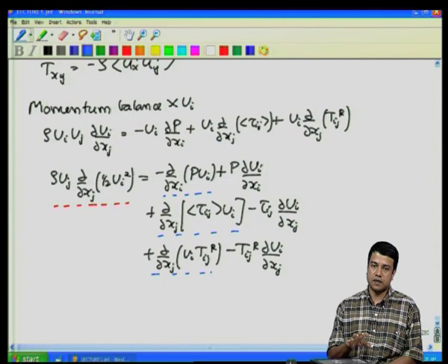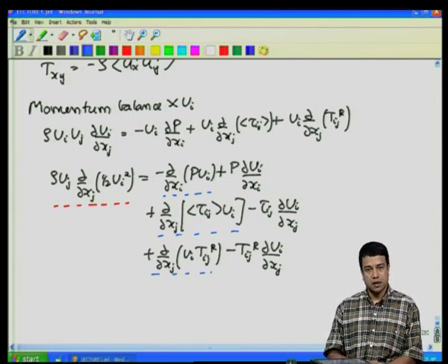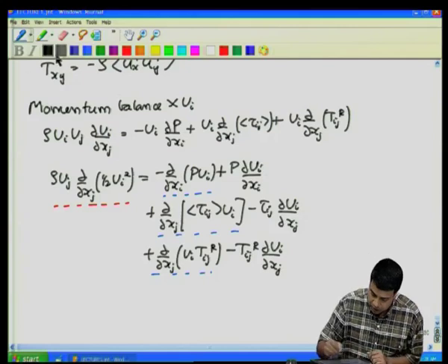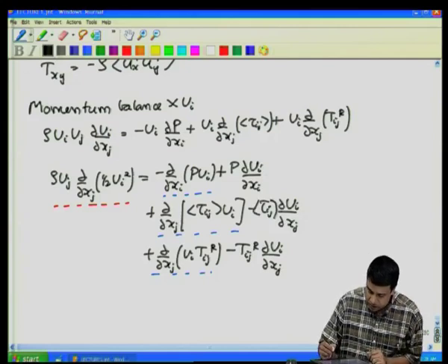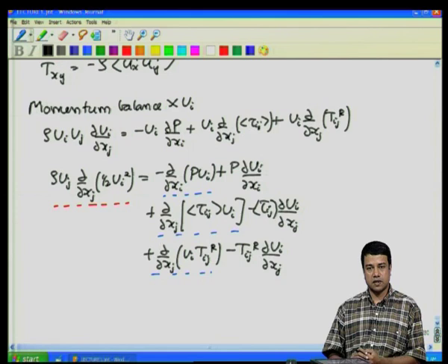The one below is the flux of energy due to the mean shear stress. And the last one is the flux of energy into or out of a differential volume due to the Reynolds stress. So, these terms do not represent a net addition or dissipation of energy in the fluid volume itself, they just represent fluxes on the surface of the volume.